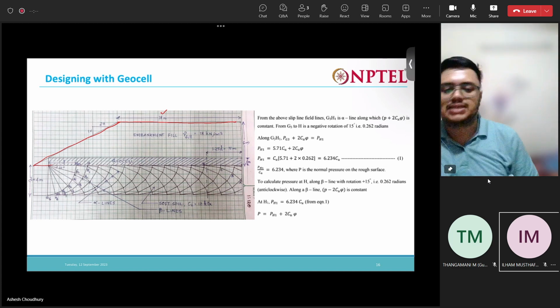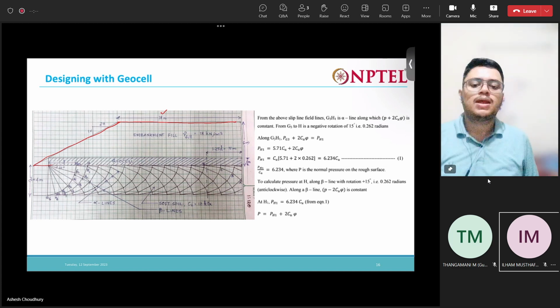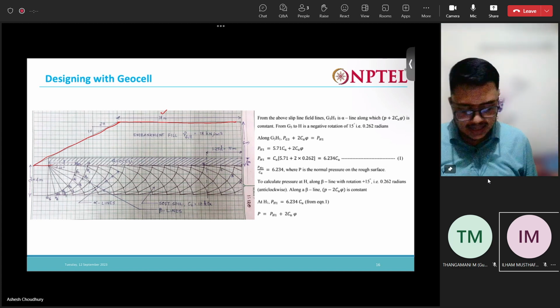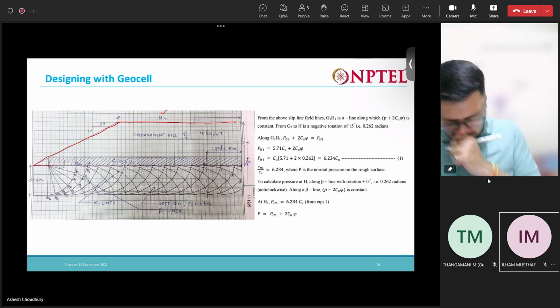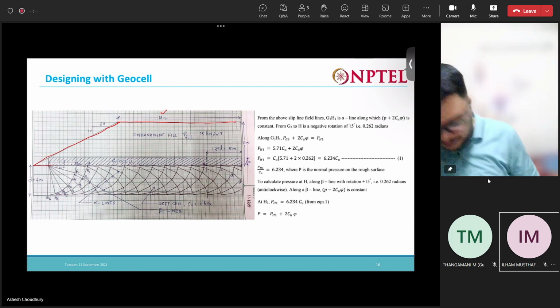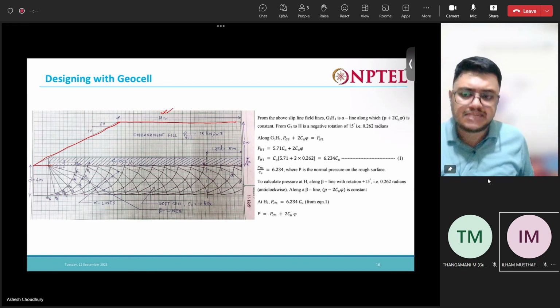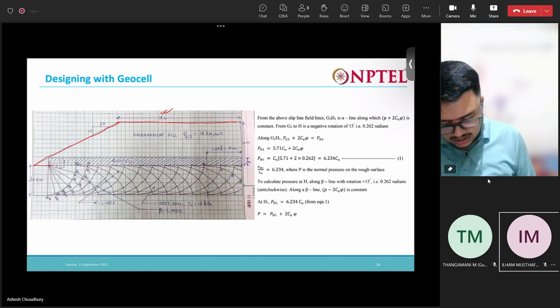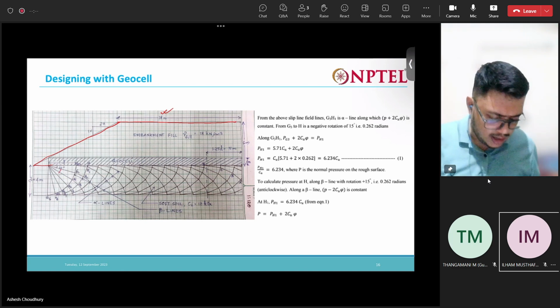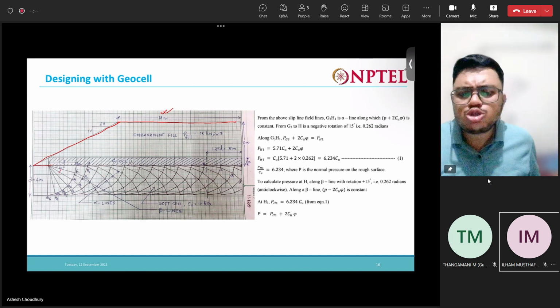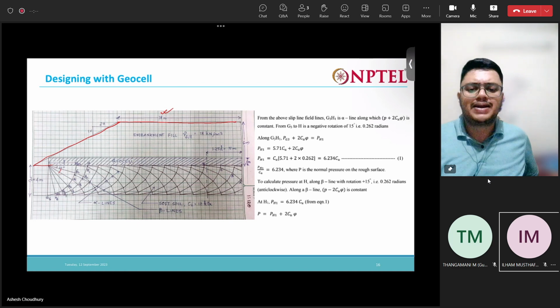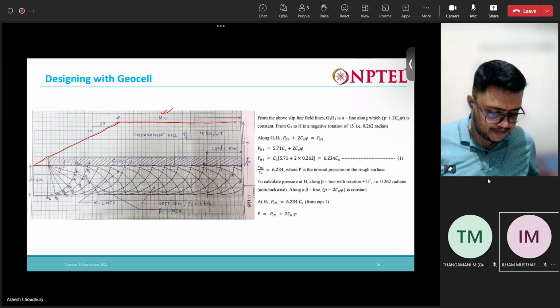So half is taken, and after that, at 15 degrees, the slip lines are constructed. All of these are 15 degrees. Various software packages are also available, which can be easily used to construct these slip lines.